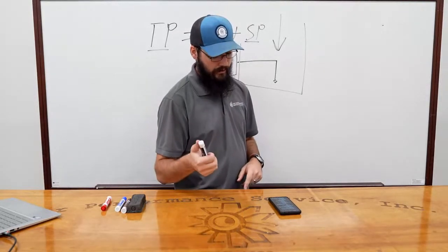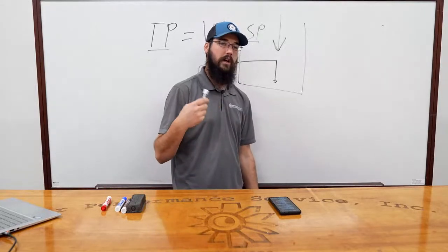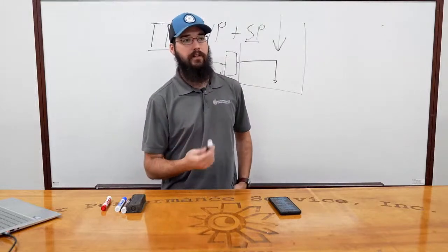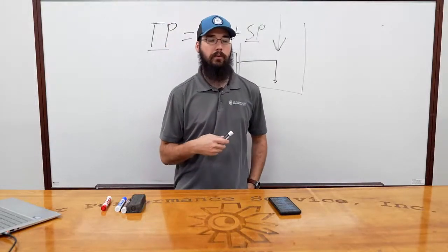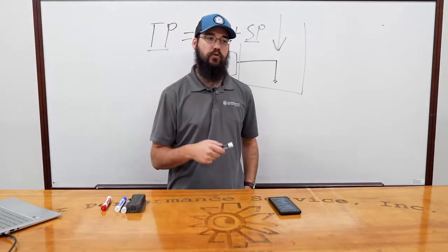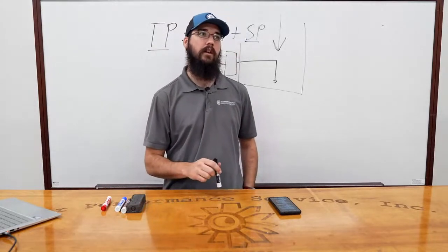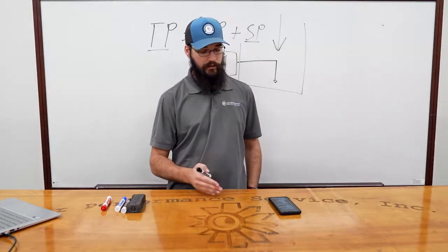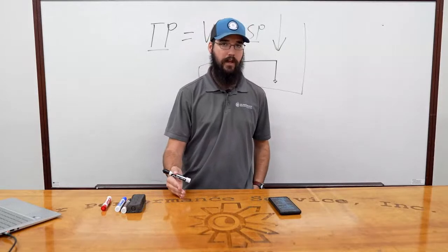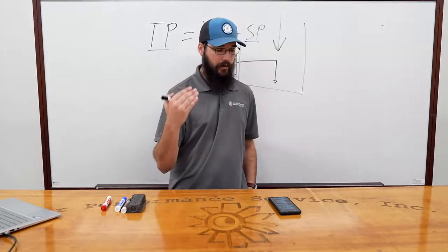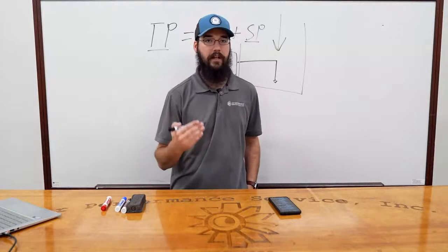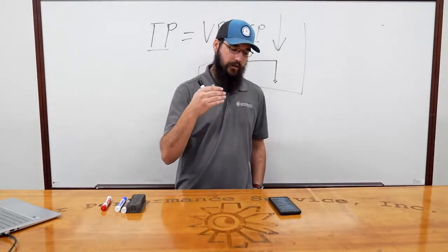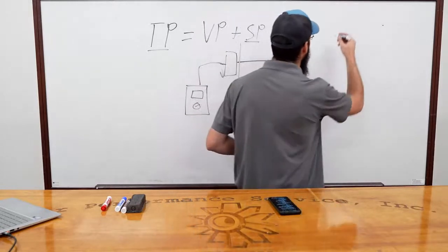Now with feet per minute, that gets into more calculations, and honestly, in my opinion, I don't find that we have to use it that much. Because of the extra measurements and the time it takes, I found in my experience that I rarely ever used that method. But if you had a system that did not have an external static chart and you needed to measure CFM on it, then you would take the